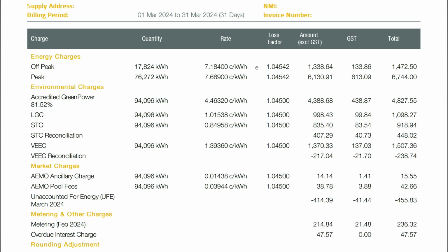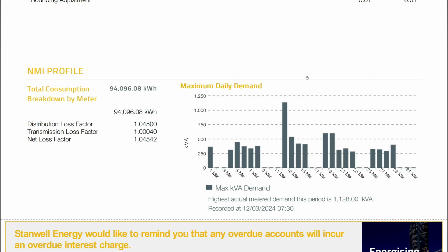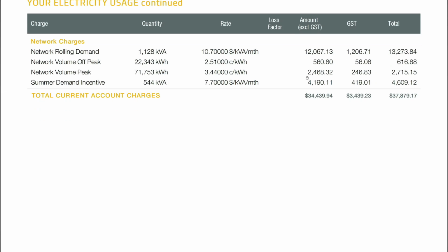We spend so much time thinking about how can we run equipment more energy efficiently, how can we slow pumps down, how can we slow fans down. We can spend so much time trying to reduce the consumption cost, the 6,000, and we aren't thinking at all about trying to manage peak demand better, which is a much higher cost.